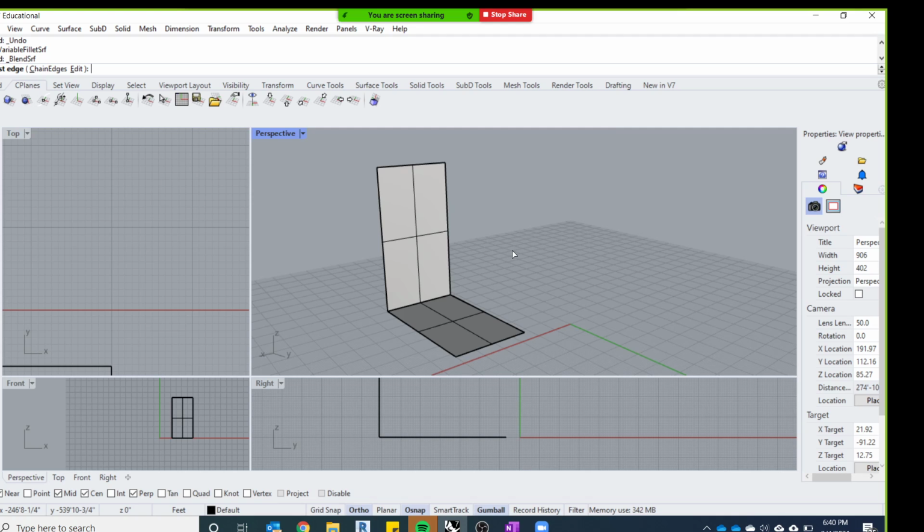And there's some other options. Oh, I'm still playing with that line. There's some other options down here that you can also play with. It's still controlling control points. So anyway, blend surface is another option to blend two surfaces together. It just takes those edges and lofts between them and allows you to manipulate them.